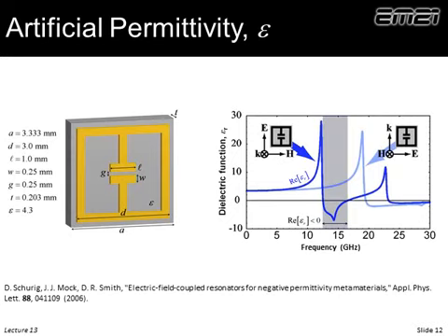But now we can control the dimensions of the wires, the gap in the capacitor, the materials. We have physical control over what frequency we have that resonance, how strong it is, and we don't have that same control working with the atomic scale lattices. And it also turns out we can get much stronger behavior from a metamaterial than we can from an atomic scale lattice.